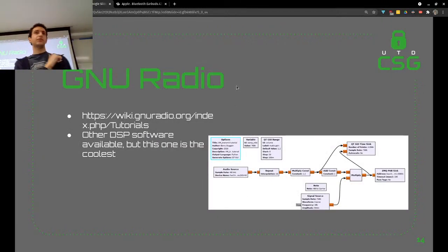So that was generated with what's called GNU Radio, which is a piece of open source software. I believe it's Linux only, but you can run it on a Raspberry Pi or whatever. And it's a nice graphical way to do digital signal processing. So you have all these samples, and they're not very useful on their own. You want to demodulate it, but there's hundreds of different protocols for that. So you can take the basic building blocks in GNU Radio and build it out.